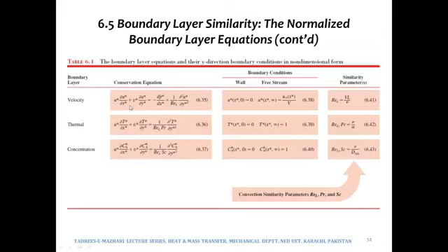So whenever we try to find the solution of any differential equation, we integrate it, and we then put in the boundary conditions. If you recall, we had done the same thing in chapter 3, where we had an equation, and then we had integrated it twice to get the temperature distribution. T was C1x plus C2 in the case of the Cartesian coordinate system, and then we had applied the two boundary conditions.